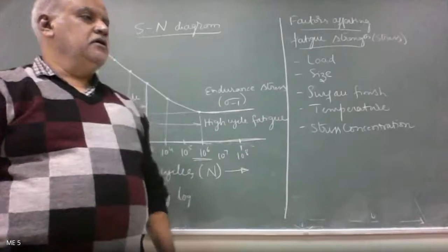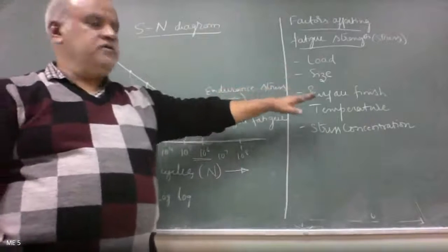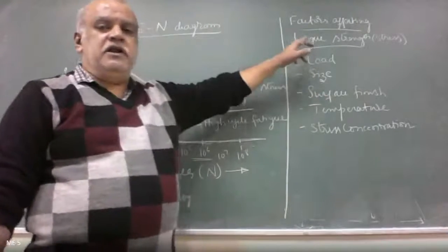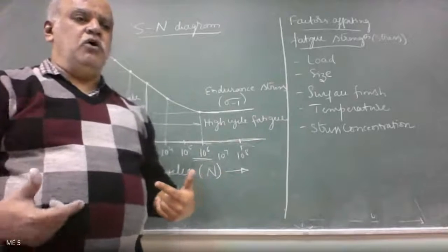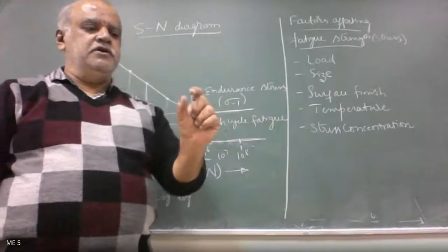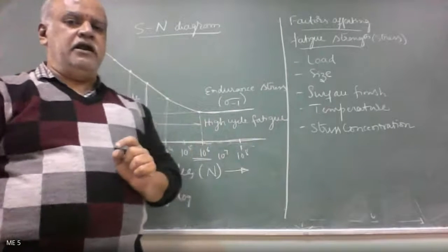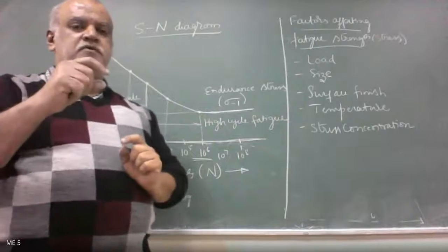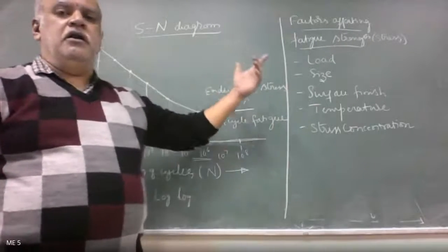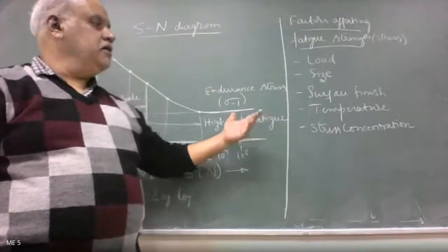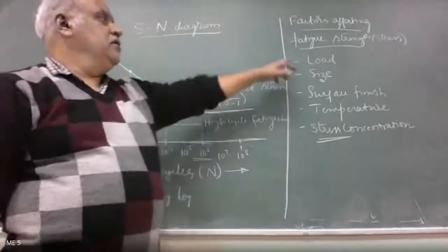Roughness average. So why we do that is because if the specimen surface finish is excellent, its fatigue stress will increase. Therefore, you have grinding operation, lapping operation, and so on. Especially in bearings, those steel balls are lap finished, which is superior to grinding, so the lap finish will have a super finish on the surface. Therefore, the ball bearing's fatigue stress will be larger. So these are the factors that would affect the fatigue stress of a component.